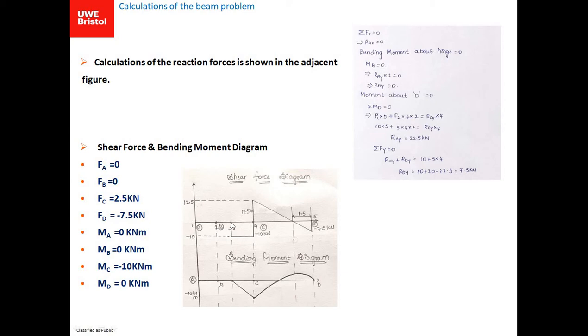So up to this location, as we know that there is no shear force, there will be no bending force acting, and from that we can determine the bending moment using the formula. And from this point, as we know that a uniformly loaded beam is applicable, for a uniformly loaded beam the bending moment diagram should be in a parabolic shape.